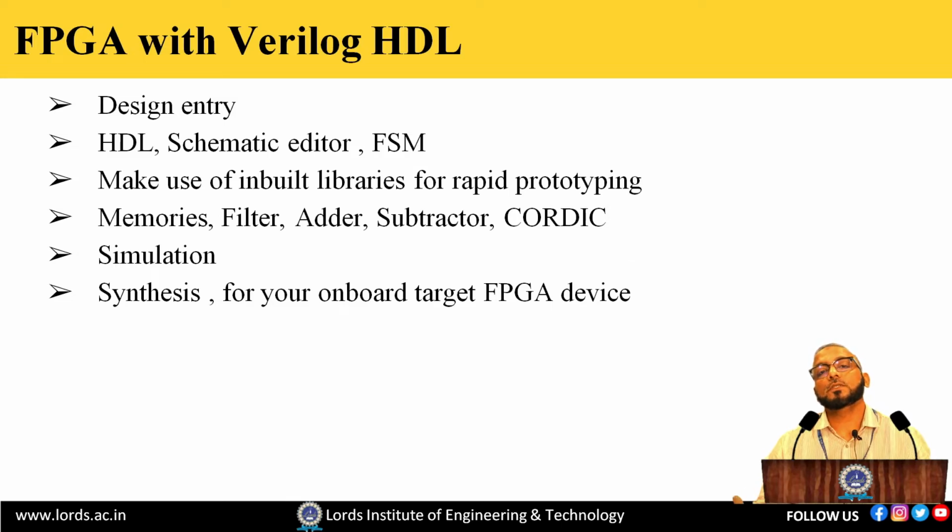After finishing this design, we do the simulation. After simulation, we need to carry out the synthesis part for our onboard design. Basically, after simulation, we are saying that our design is ready. While synthesizing, we come to know how many gates are involved, and that generated report is very important. Based on this, we dump the program onto an FPGA, which is what emulation and development boards are commonly used for.